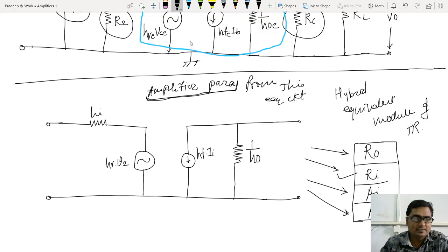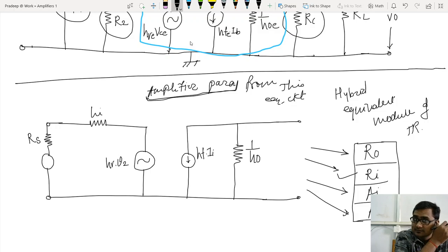First thing I need to do is apply some input signal. So here I will apply an input voltage. This is the input voltage that I am applying. Then I have to draw a small series resistor RS. Yes, that is a must. Another thing to put in the circuit is a load resistor.